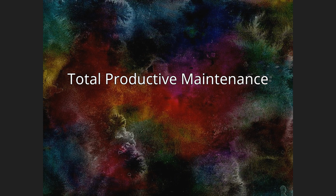Combining OEE with focused improvement converts OEE from a lagging to a leading indicator. The first focused improvement stage of OEE improvement is to achieve a stable OEE, one which varies by around 5% from the mean for a representative production sample. Once an asset's efficiency is stable and not impacted by variability in equipment, wear rates, and working methods, the second stage of OEE improvement, optimization, can be carried out to remove chronic losses. Combining OEE and TPM focused improvement tactics creates a leading indicator that can be used to guide performance management priorities.